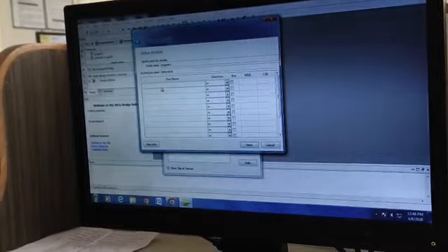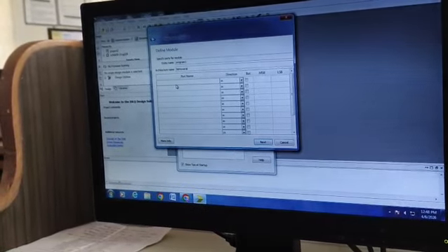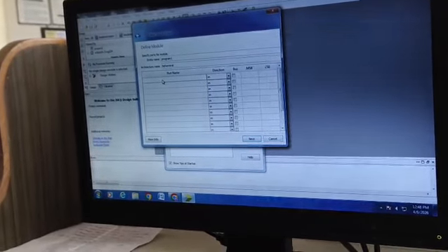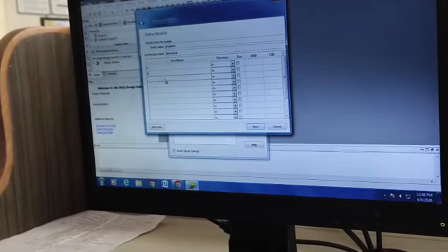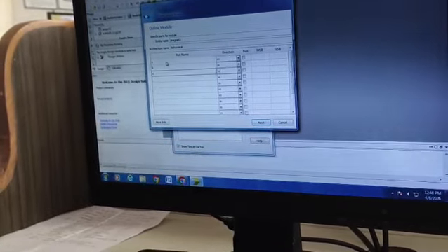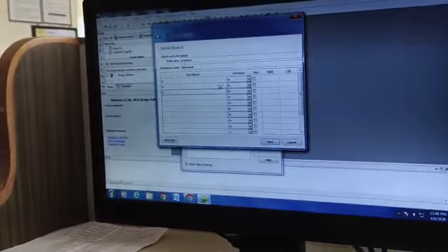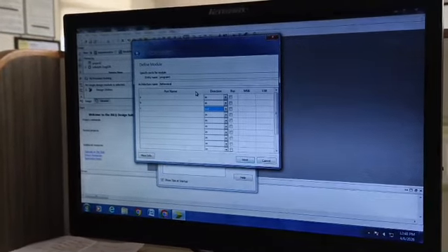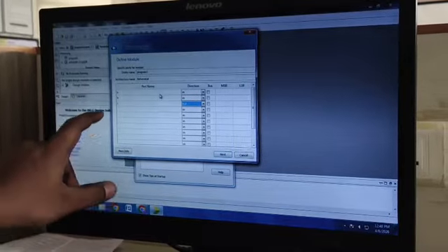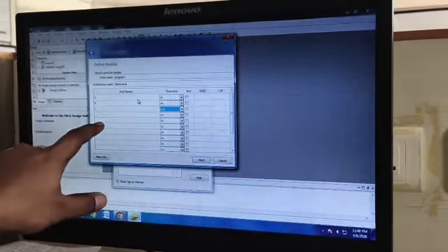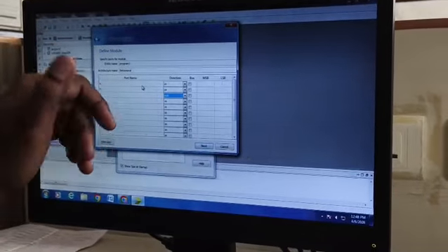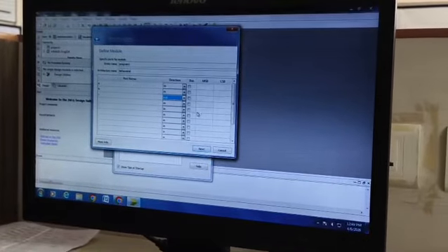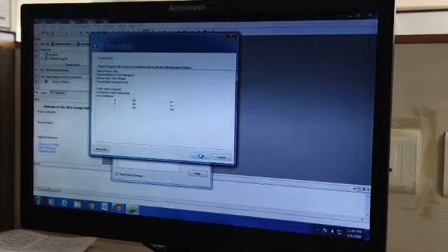A new wizard opens where we have to give the port names. First we are going to try the OR gate, which has two inputs and one output. Name the ports A, B and C, where A and B are inputs and C is the output. So A in, B in, C out is the direction we select. For a half adder, you would give A, B, sum and carry, where A and B are inputs and sum and carry are outputs. We are creating the ports and giving the names, then Next and Finish.